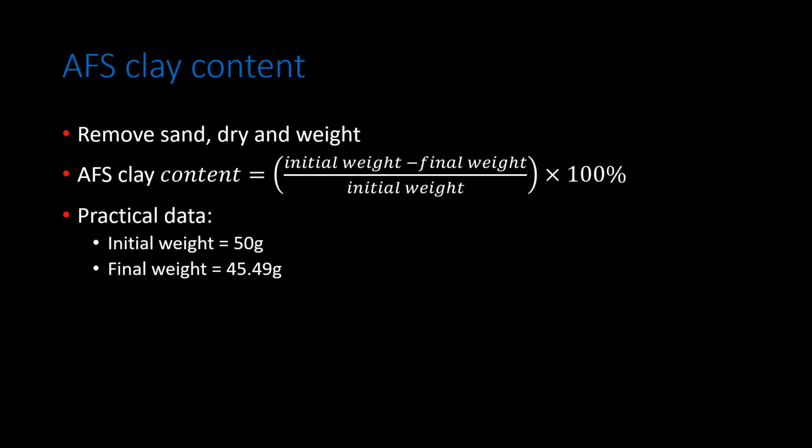After the water is clear, remove the sand and dry it at 110 Celsius for about 2 hours. Then measure the weight. Using this equation and the practical data, you can calculate the AFS clay content.